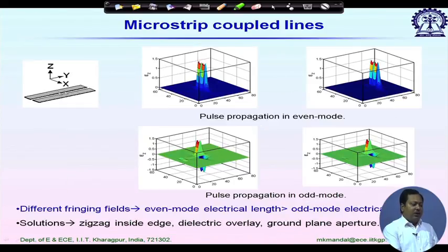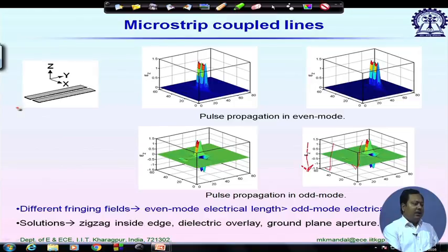Let me show you the time domain propagation. You can see the strips, and in this figure the propagation direction is y, and we are placing two millimeter wave sources at this edge on the left hand side, right here. So, let us first consider the even mode excitation. That means these two sources are in the same phase.